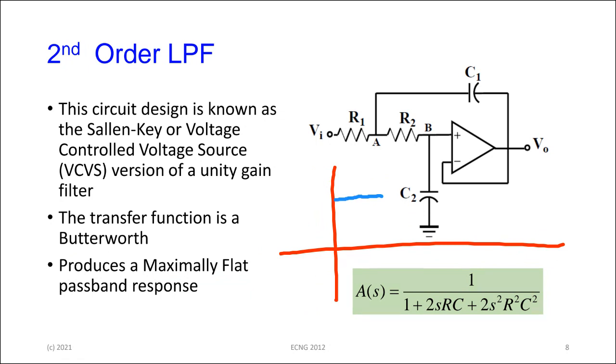And then it changes from the transition frequency, at the cutoff frequency, it changes from pass to stop band. But of all the filter designs, of all of the possible arrangements for this, and there are many, and we'll come up with another one tomorrow just to show you, the Butterworth gives you the flattest response. But the trade-off for that is that this transition here is relatively shallow.